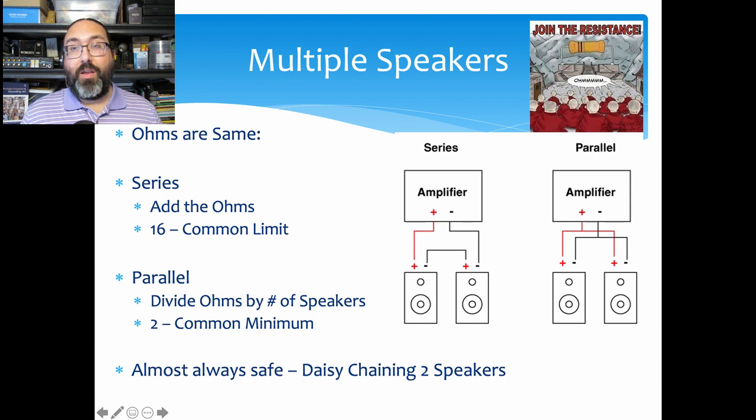16 divided by 4 equals 4. So you can use most amplifiers as long as you use all 4 of these speakers in parallel like they are designed.